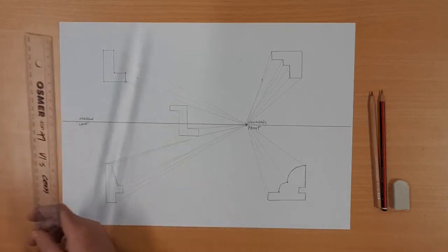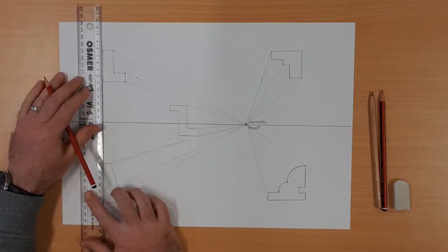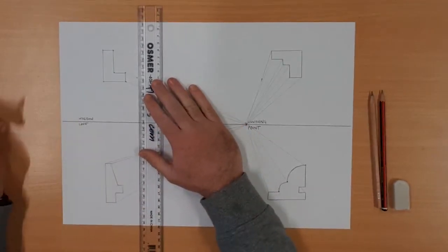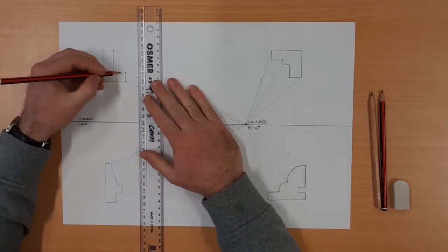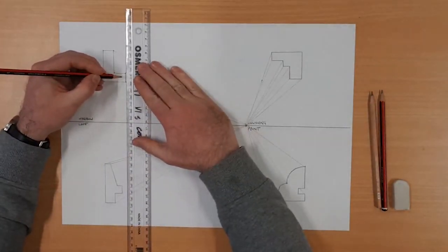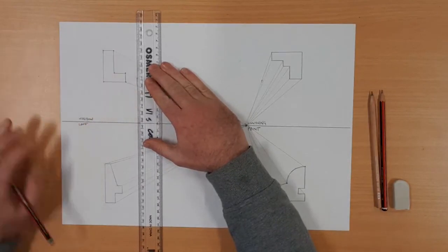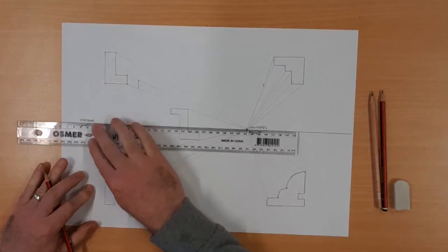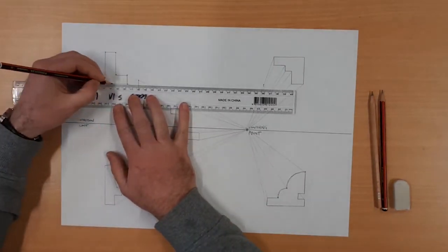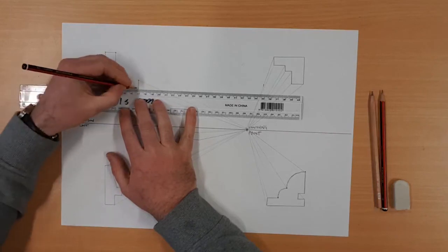And then the only other thing you're doing is replicating or copying whatever the angle is that's on that same face. So here, it's running vertically. And so I'm just going to pull the ruler back and draw a vertical line there. And then same thing along the bottom, that bottom face. Pull it out, it's going to be horizontal.